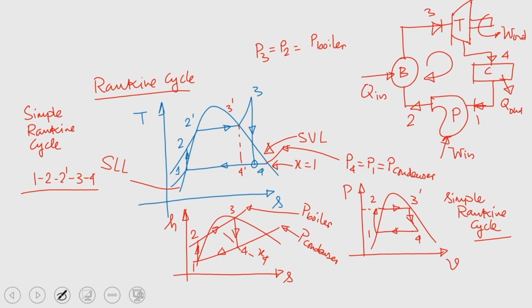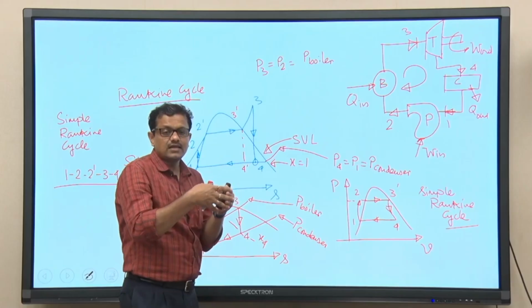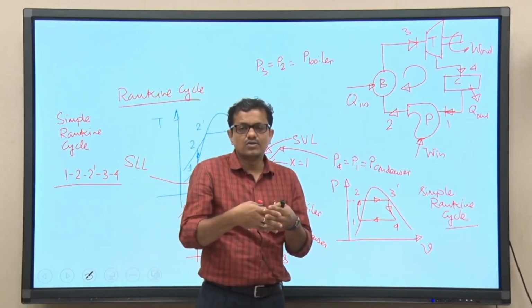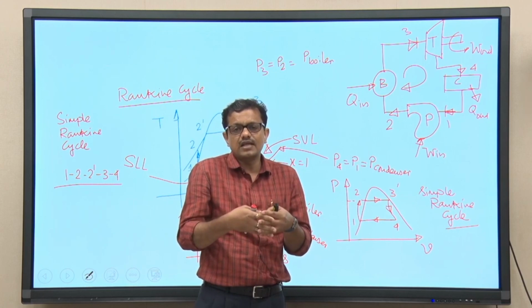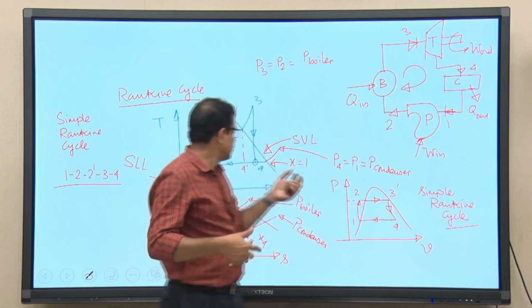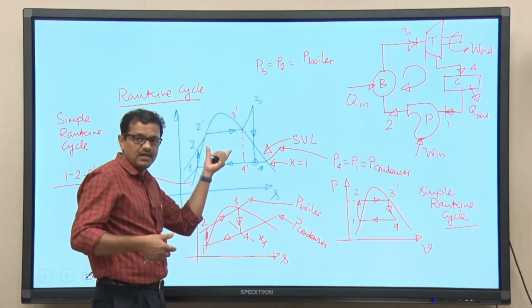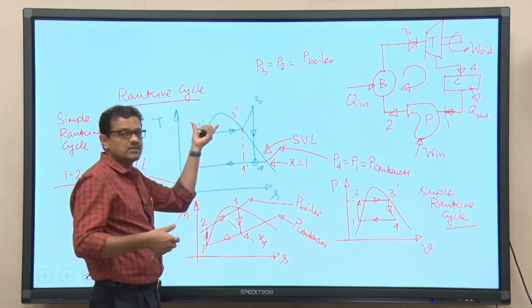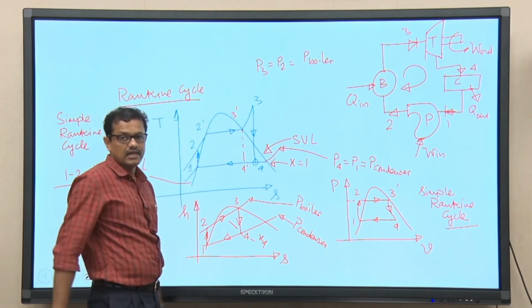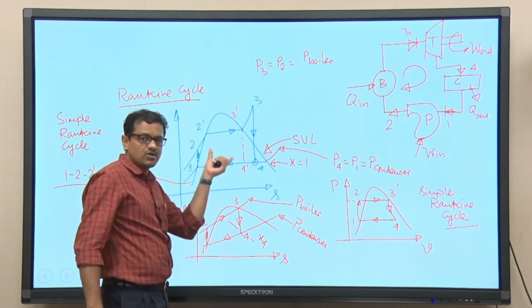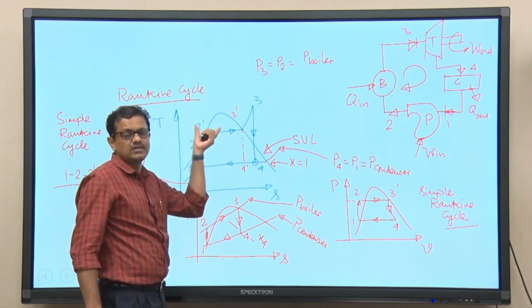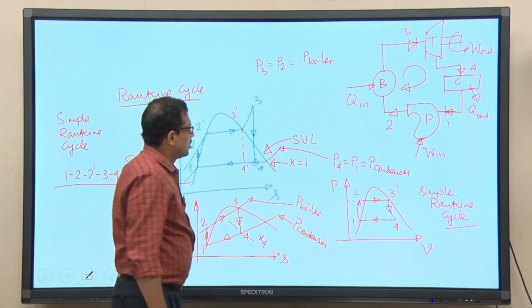So, this is the simple Rankine cycle. The idea is we can eliminate the problem associated with the ideal Carnot cycle. If we can eliminate it, the cycle becomes more practical. So, the processes which are there in real practice can be compared by using the processes which we have mapped in the TS plane, but all these processes correspond to the Rankine cycle. All these processes constitute together to form a cycle which is known as the Rankine cycle. Okay.